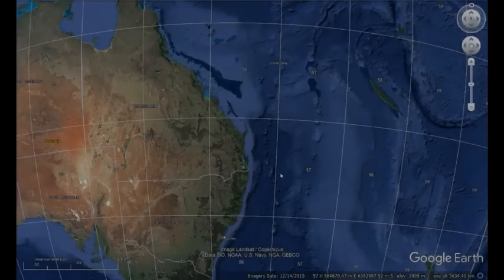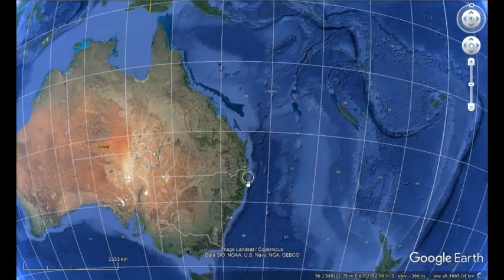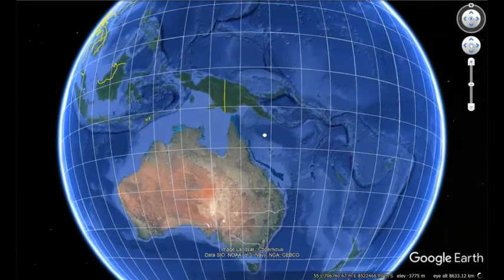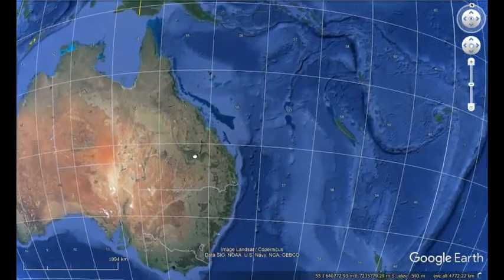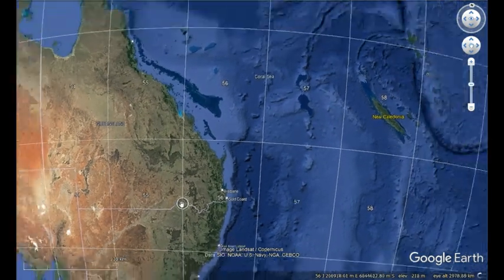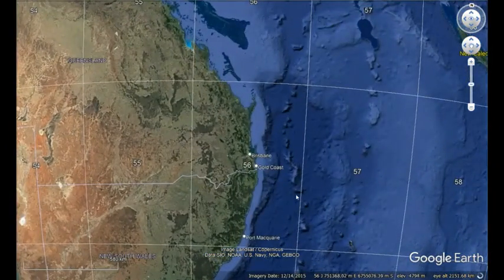So I loaded the UTM zones on Google Earth, so you can better understand how these cylinders intersect with the Earth. Those are the limits of each zone. In total, we have 60 zones, and they are 6 degrees each.